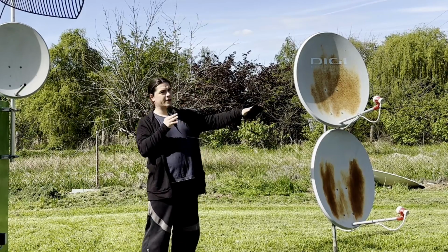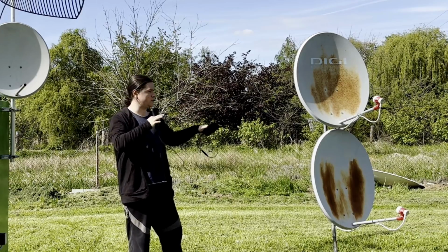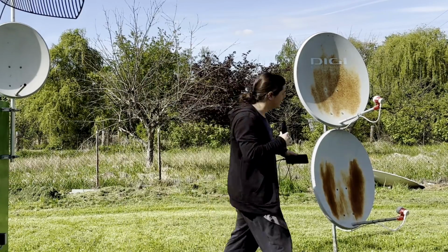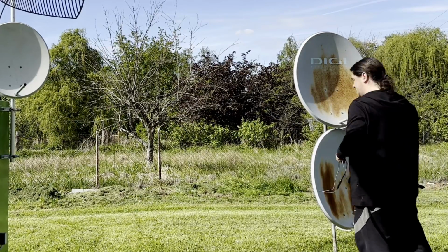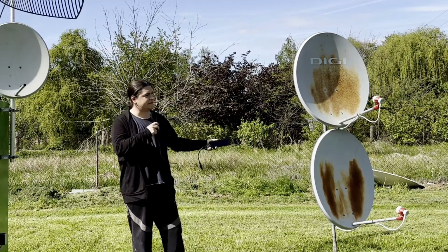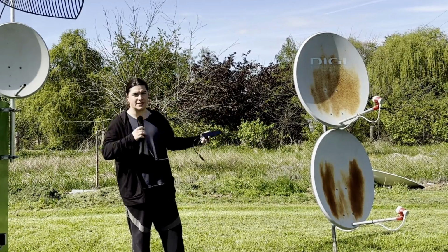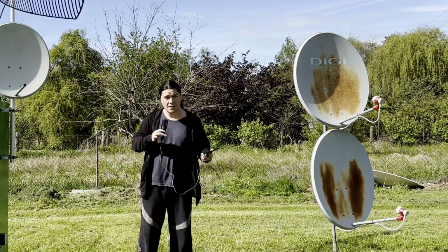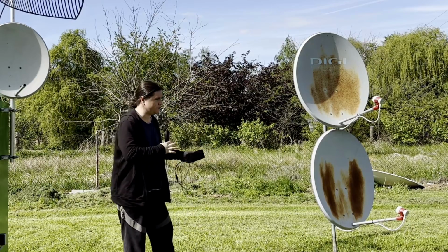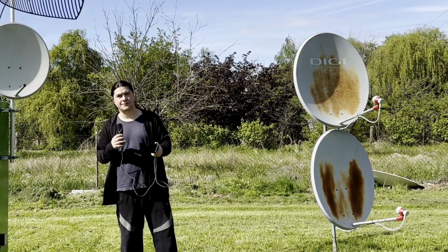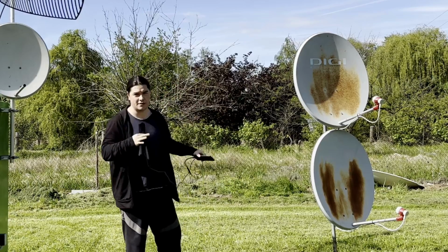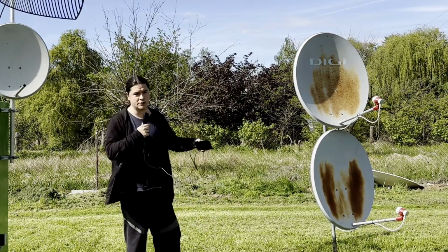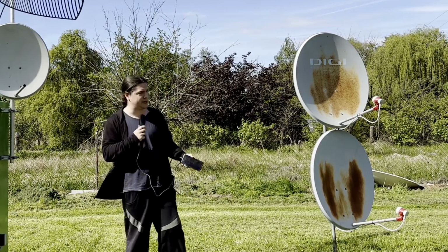Usually these LNBs are going to be marketed to only work from up to, I don't know, do they have it? 10.7 gigahertz up to 12.7. That's actually the TV range, right? The Ku band TV range that was written on the LNB, but realistically they can go down to 10.5. I'm just mentioning this specifically so you don't get some special kind of LNB that only goes down to 11 gigahertz or 12 gigahertz, because those also do exist if you just browse AliExpress for it or something.